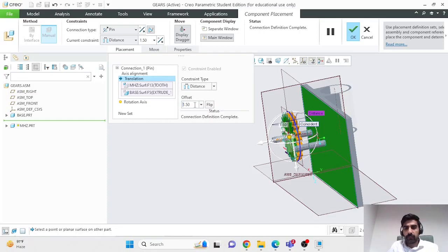I think I'm currently working in inches. I'll make note of that, which is not a good practice. You should have been working in mm, because everything you designed was in mm. So don't be lazy like me and work in the same system of units.